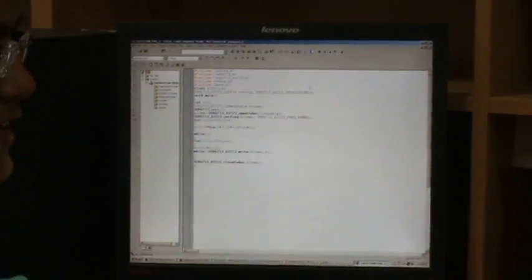Here, the experiment is on receiving a sine wave and processing it. The input can be given with a maximum of 500 millivolt to 1 volt peak to peak. Generate a sine wave of 1 volt peak to peak and check with the CRO. This is to be given to the DSK. How to connect the signal to the DSK, modify the program, explain the significance of the addition of each line, amplify the signals and observe the output is the main objective of our sine wave generation. And then next we will proceed with some effects of changes in sampling rate.